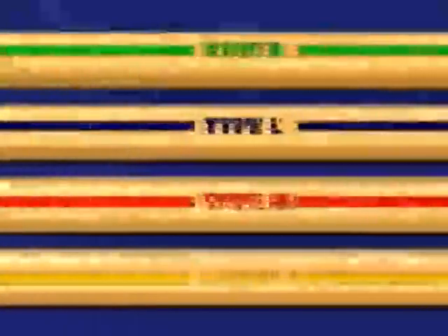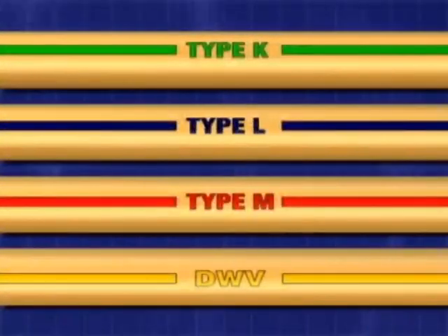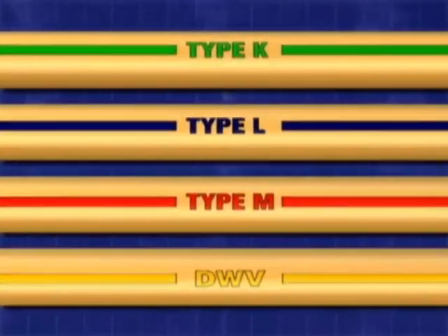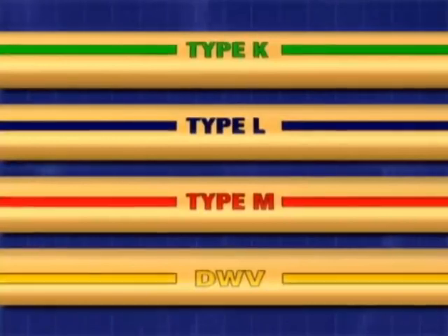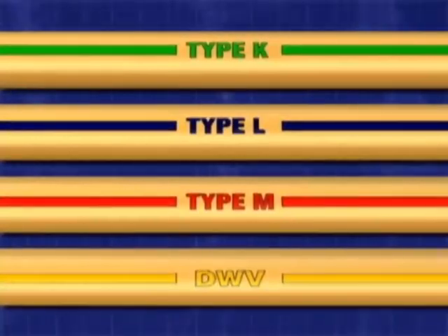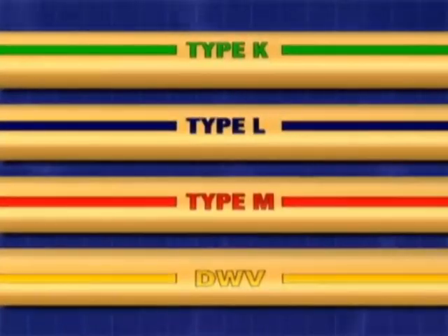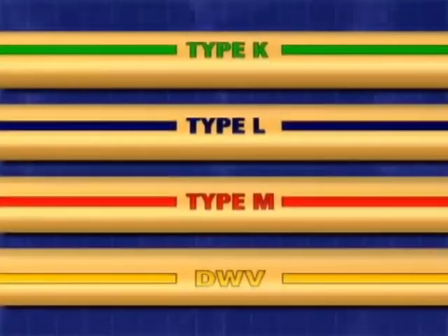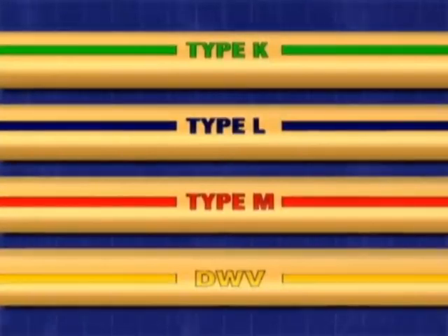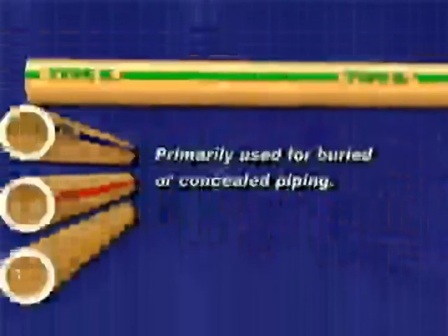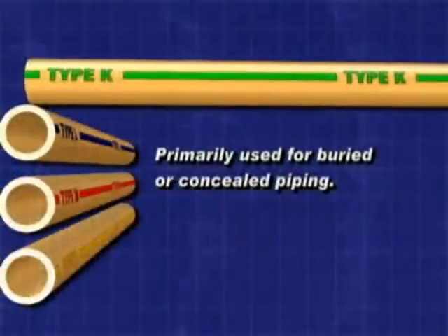Flip on to the next page, copper tubing. Let's look at copper tubing. It is one of the most popular plumbing modes of getting water into and out of the house. If we look at the first paragraph there, we'll see that there are four different designations: the K, the L, the M, and the DWV. Let's underline the second sentence. Type K has the heaviest wall thickness, and type DWV has the thinnest wall. And L and M have in-between thicknesses.